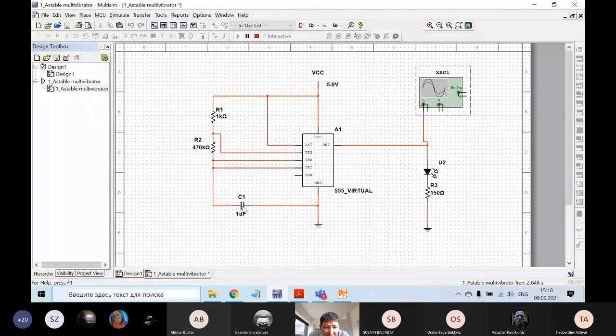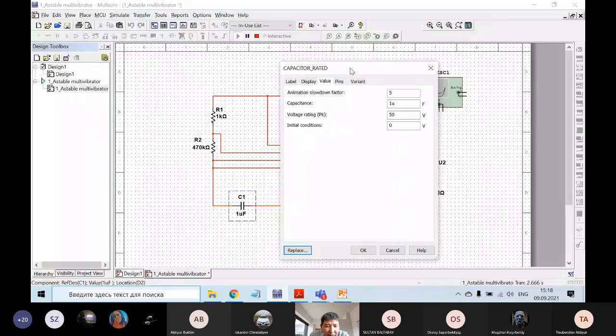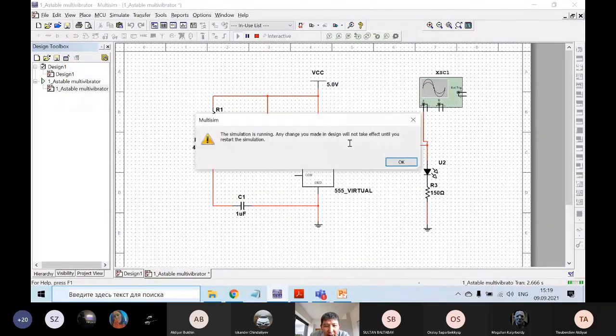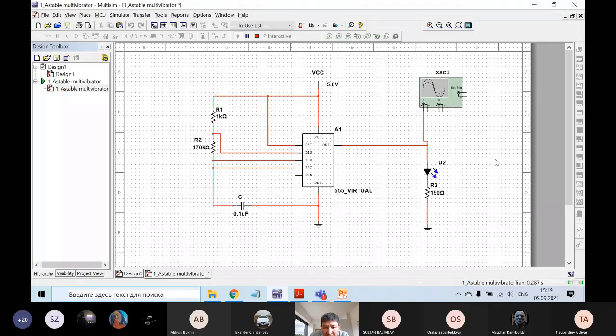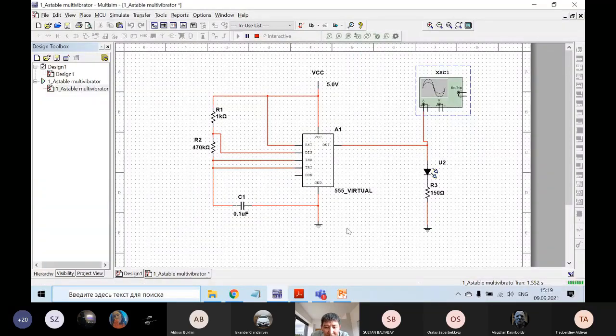Okay, let's change the frequency. How can we do it? Just adjust this capacitor. Capacitor, I said in Russian, it will be конденсатор. It has capacitance, емкость. For example, we will decrease it. Previously it was 1 microfarad. Now I change it to 0.1 microfarad. So I will start again. What happened? What do you think? Frequency is increased, right? Yes. Let's see here, can you see it in the oscilloscope? Okay, you will do all of this in the lab. It's just some example of free-running clocks.